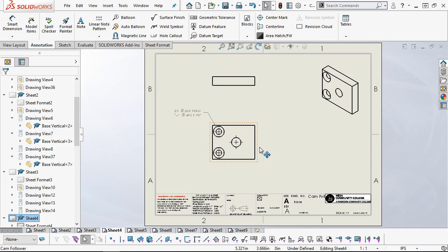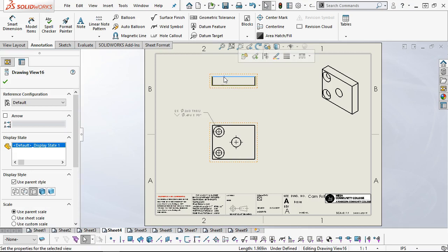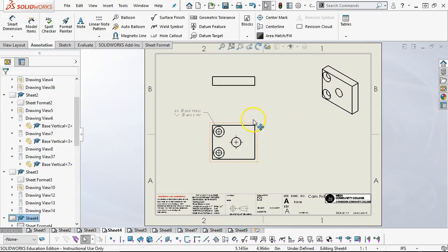So you pick your A datum. We're looking at this based on the way that this folds over. Probably the bottom of the part, which would be the top of the view. So kind of this back surface would be the one that I was going to pick up anything for flatness. It would be in that area, or we could experiment with applying some datum targets, but it's pretty small, so I don't know that the datum targets really apply here. Keeping it in the range right around that point.